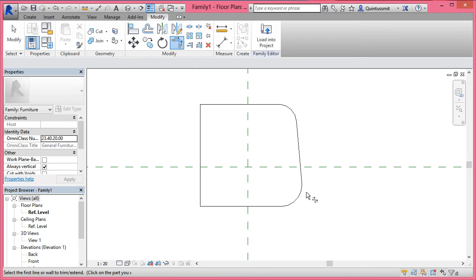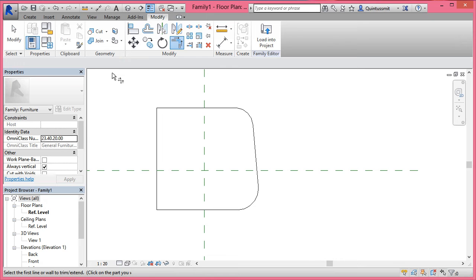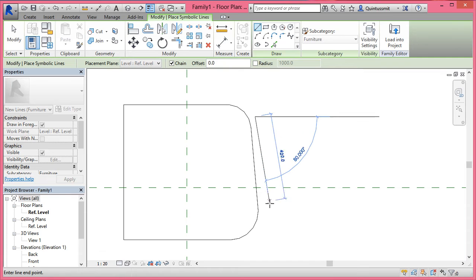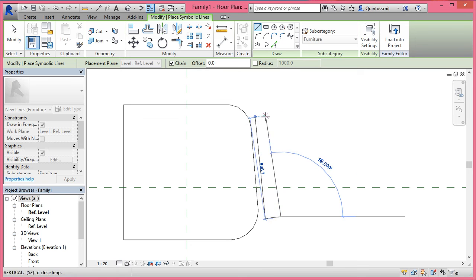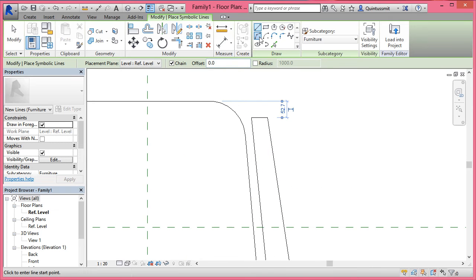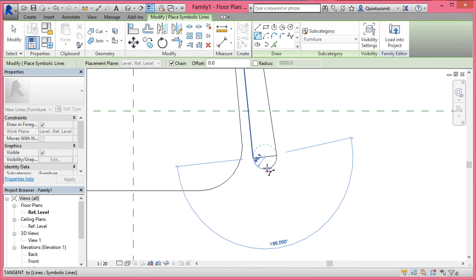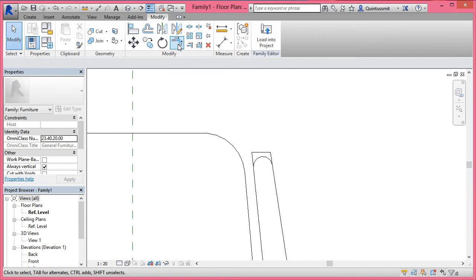Now you can see I'm only building one side of this. Basically when I'm done here, I'm going to mirror it over to the other side. So I know it looks exactly the same. Also it saves time. Going to line again, just to do the armrests. Obviously the exact look of this isn't that important. It's more about having something to work with. So I'm making this up as we go along here. You could delete that using trim and extend again, just to trim those lines to each other.